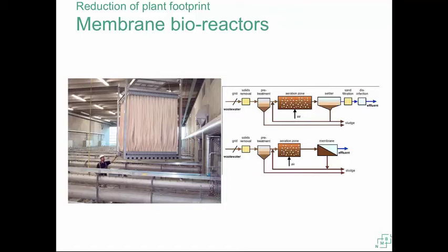But there's a process called membrane bioreactors. Instead of having a sedimentation process, we can put a membrane here. This is the sedimentation tank. This is the membrane process. So you can reduce the separation time down to maybe half an hour, something like that. So thereby you can reduce the volume and area of the sedimentation tank by maybe 5 times.